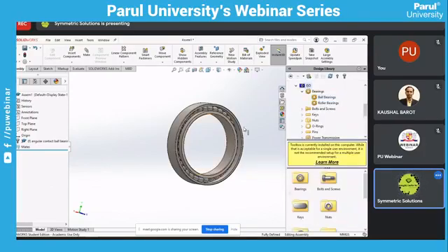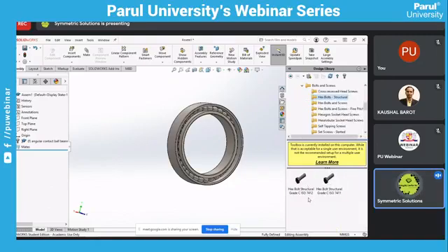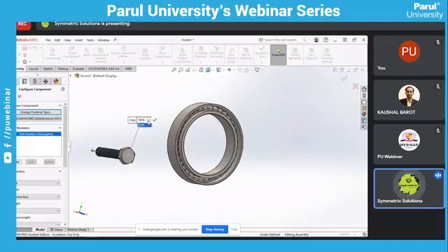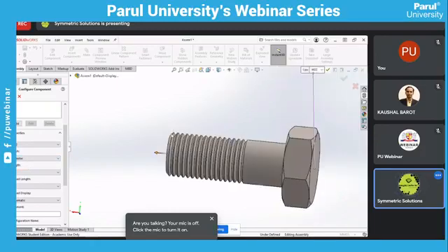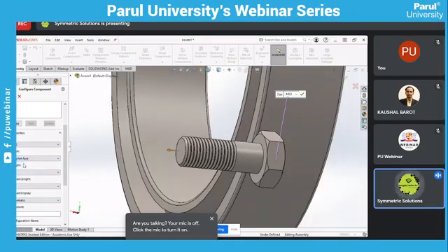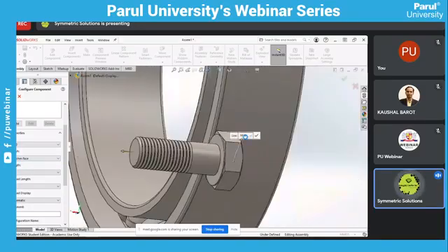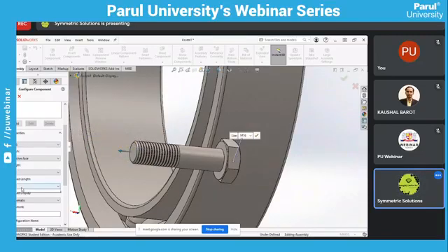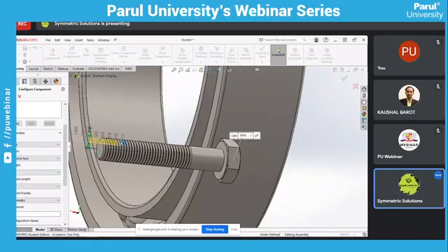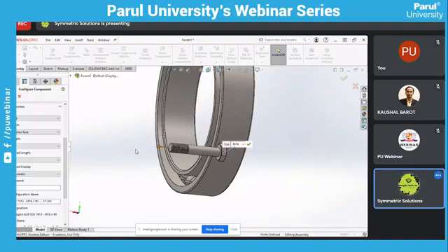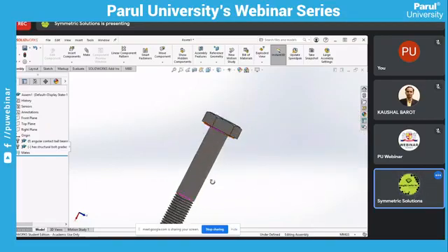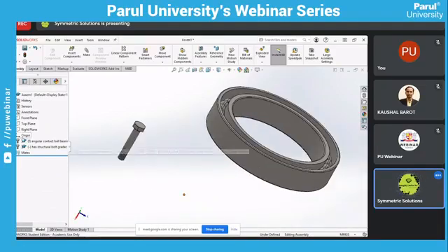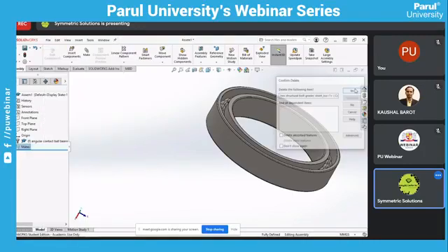Again, if you want to call some fasteners, then bolts and screws. If we need some hexagonal bolt structural, we have hexagonal bolt structural grade C ISO 7412 or 7411. This is 7412. Now select your size, M22. Define size as well as washer face or chamfer face. If we need some washer face, so this is washer face. See, length, how much length you need, like this. Thread length and schematics. Thread display, yes. Bolt is also automatically created. This is all from the library toolbox. So no need to create manually.